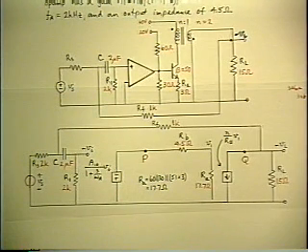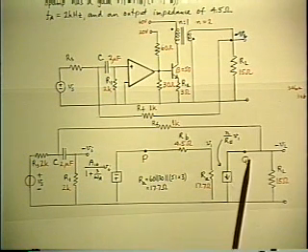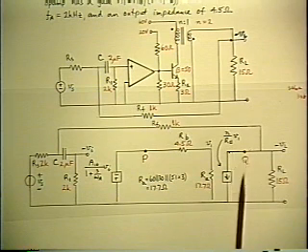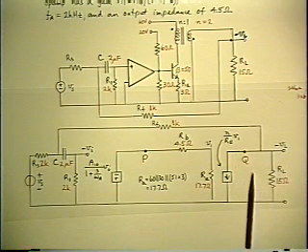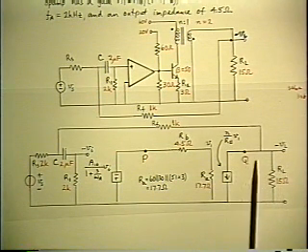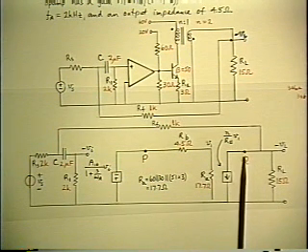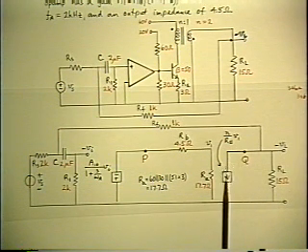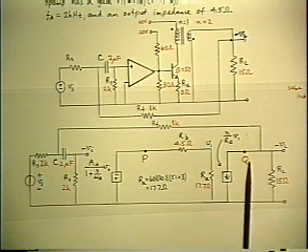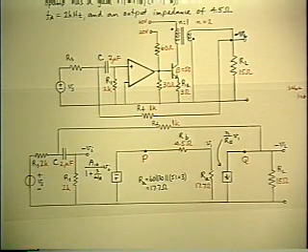So that's a possibility. Point Q is also a possibility. The opposite type. That would be okay for doing shunt current injection because it's right at the output of an ideal current generator with infinite impedance, so that's appropriate for shunt current injection. Either one of those would be all right. Can you see anywhere else you might do injection?